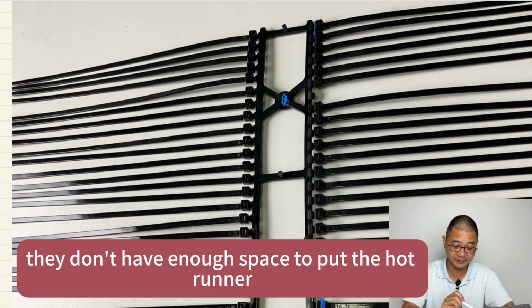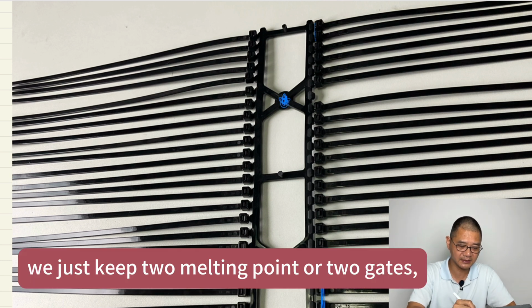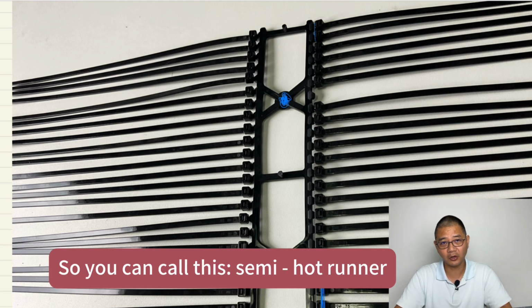They don't have enough space to put the hot runner. So for the cable tie, we just keep 2 melting points or 2 main gates for the melting plastic. So you can call this a semi hot runner.